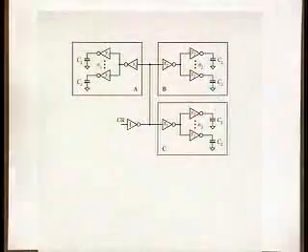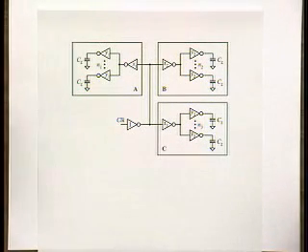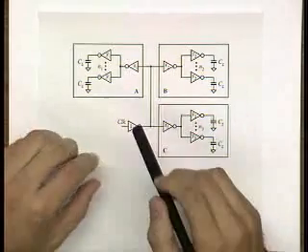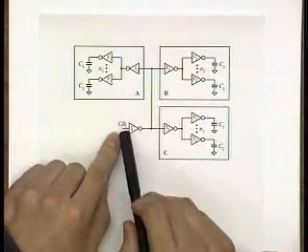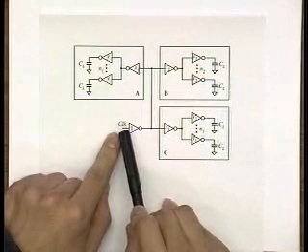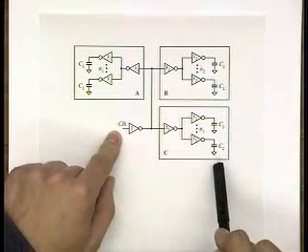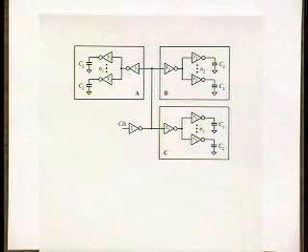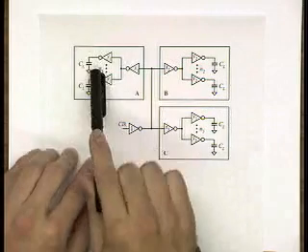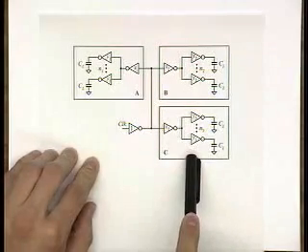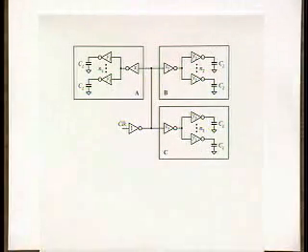Now the question is, these need to work at the top level. So I need to tune my clock tree a little bit to make sure that I have the same propagation delay from my external clock that comes in here to all the clock nodes over here. Because what you really want is a perfectly synchronized system. So you have all your clock edges aligned such that when your signal travels from block A to block C, you still have well-defined reference points for those signals. So that's the idea.